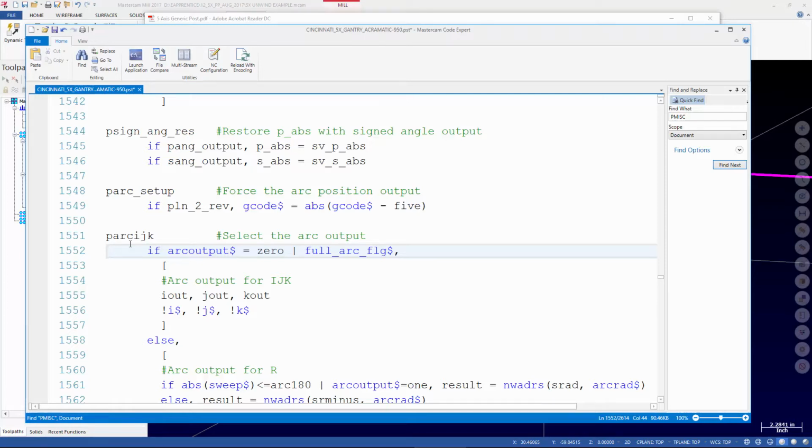Well, actually, when we start with the Trunnion on Thursday, we're going to start from scratch, and we're going to lay out the whole Trunnion. But we'll go through and we'll test it, and I'll show you what the difference is. So really, we have to make sure that the shift settings in the post match the way that we're setting up the job in Mastercam.